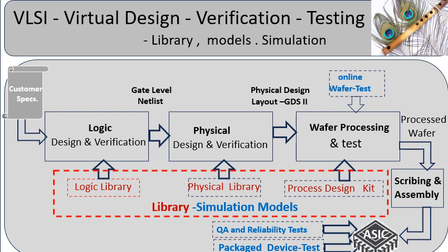The logic design focuses on functionality of the chip. It transforms specifications into RTL-level functional code. The physical design transforms code into the chip's physical layout design that can be fabricated in the targeted foundry. The foundry converts the layout into a silicon chip that realizes the desired electrical functionality.